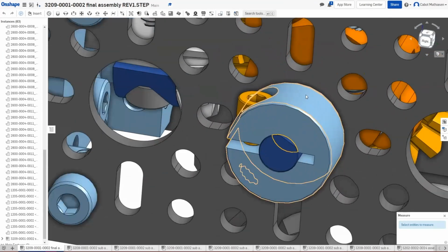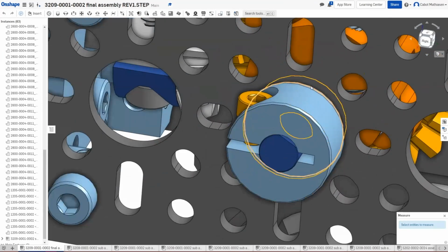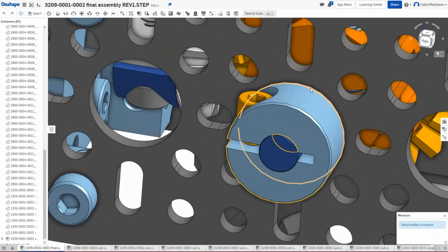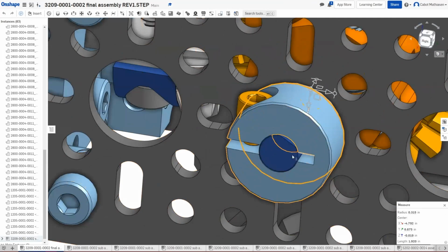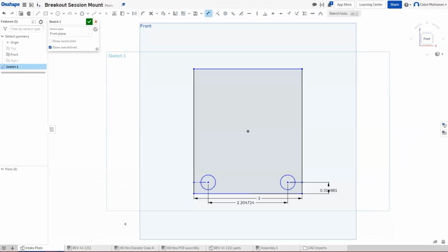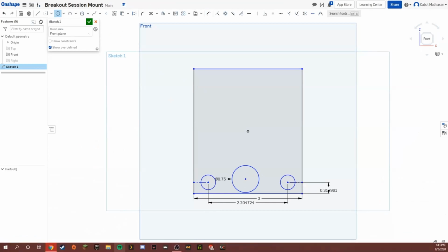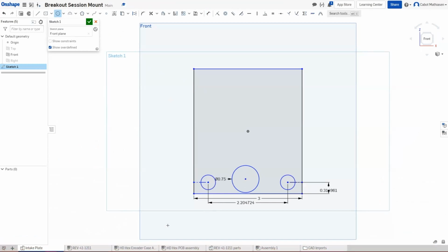Okay, so now I need to measure the radius of this clamp, so we can put the hole in the plate. So here it says about 0.315, so double that for it. But since you also see that screw there, that goes past it. So I'm gonna try 0.75 and see how that goes, and then I can always edit that later.